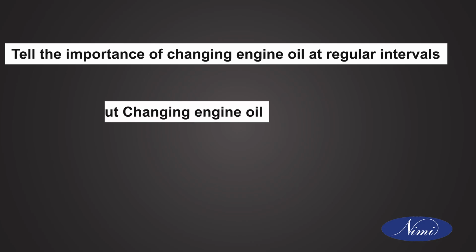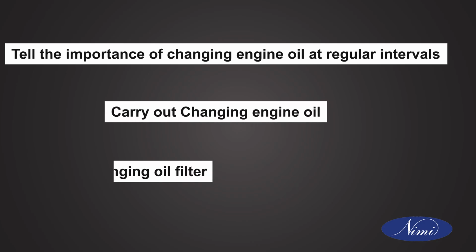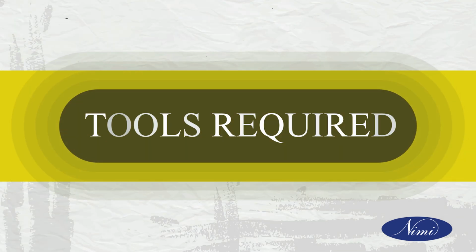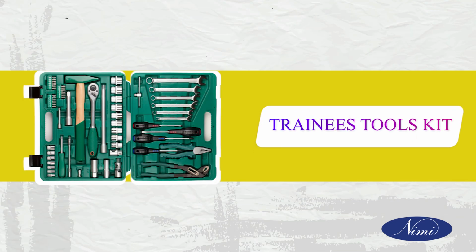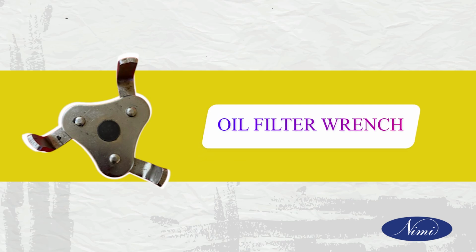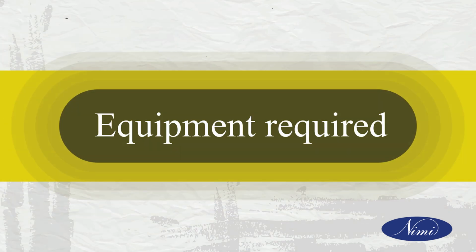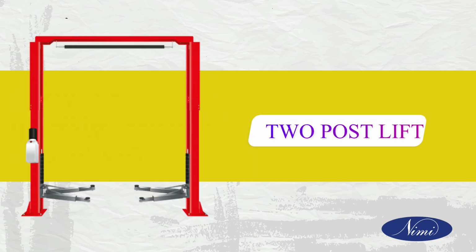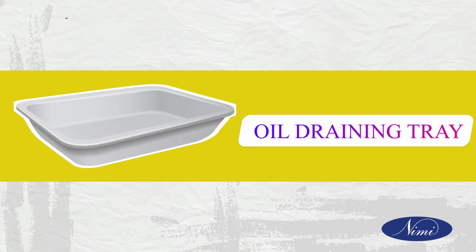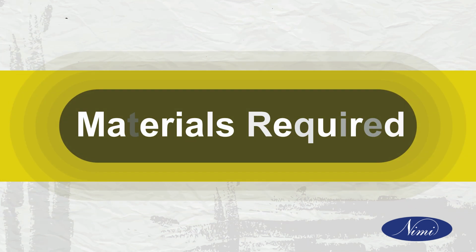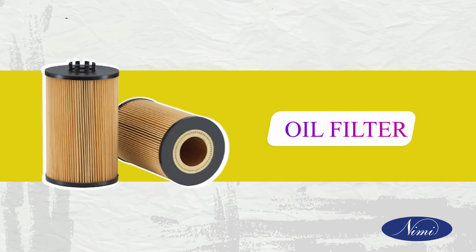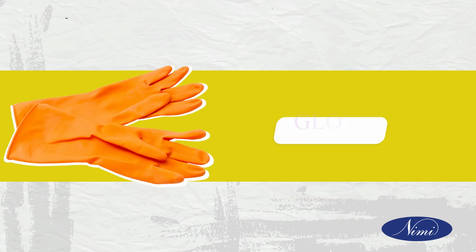carry out changing engine oil, and carry out changing the oil filter. Tools required: trainee's toolkit, oil filter wrench. Equipment required: a vehicle in running condition, two post lift, oil draining tray. Materials required: engine oil, oil filter, soft cloth, gloves.